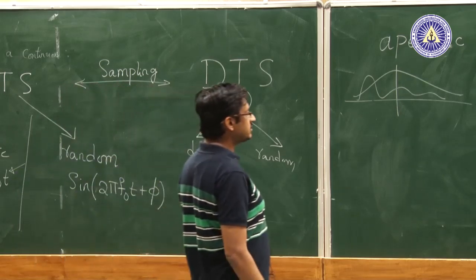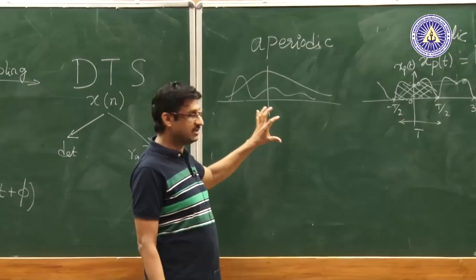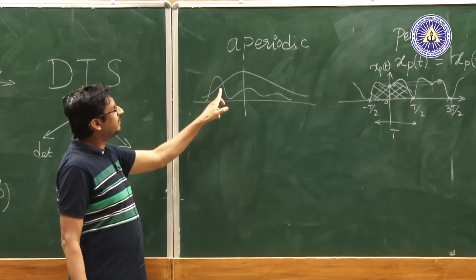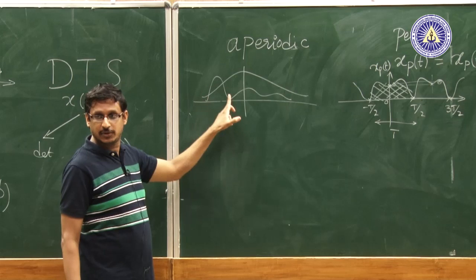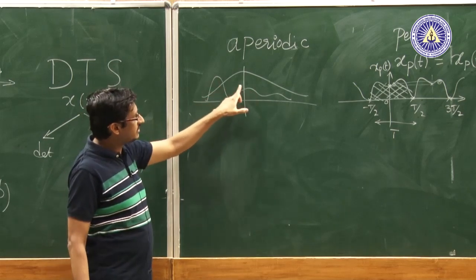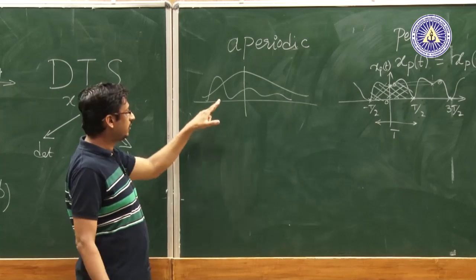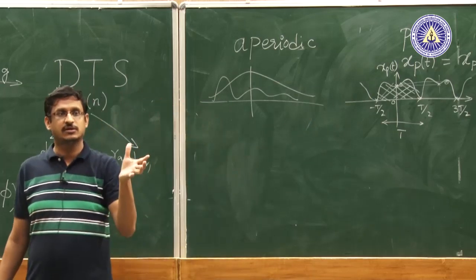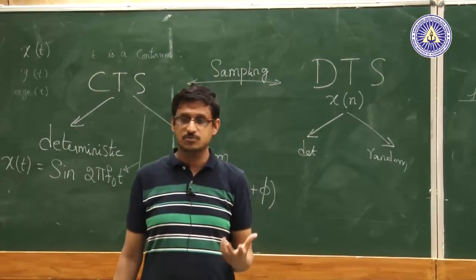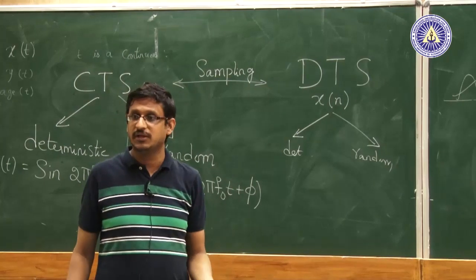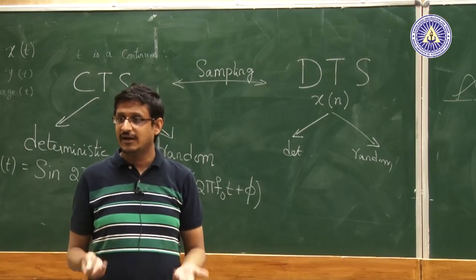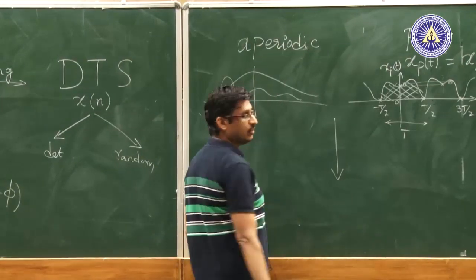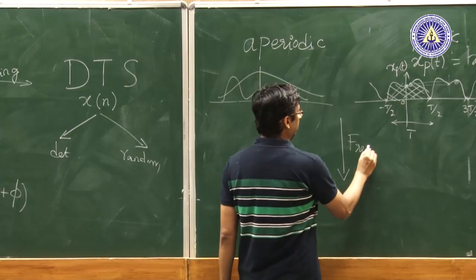So, to understand those concepts wherein we cannot just by looking at the signals say that there is a periodic signal, because for example, here you can say that there could be a periodicity because there is some sort of a periodic variation, but this is also something that is getting damped out there, right. So, there is periodicity, but the function itself is getting damped, or the signal is getting damped. So, there could be periodic in some sense, but I do not know what the period is, because by looking at this it is quite hard to say what is the period and whether there is a periodicity in the underlying signal or not, right. To answer questions like that, you have to go to the complementary domain, what is called as frequency domain, okay.